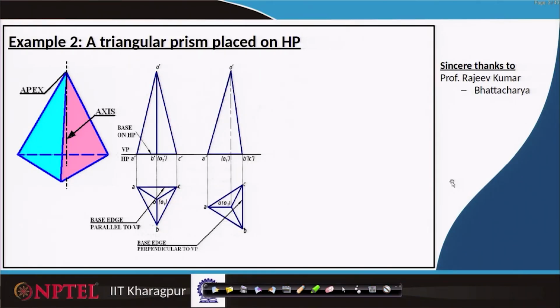Let us rotate one of the base edges. So, instead of having this one, let us have an inclined prism. In that case, from the top view, this point A maps there, B and C coincide, that is the reason for B prime, C prime. O will be visible, and there is a line which goes and joins that point. So, all the way from there we connect it.